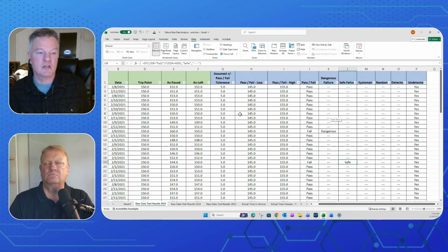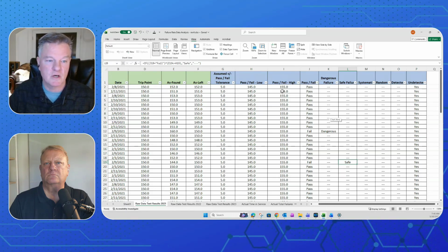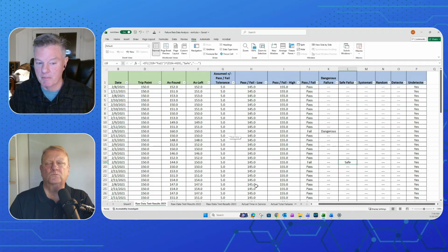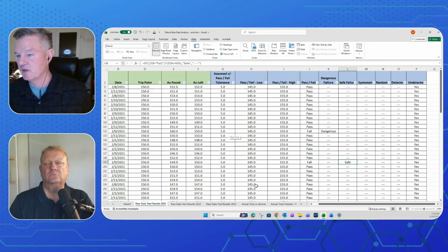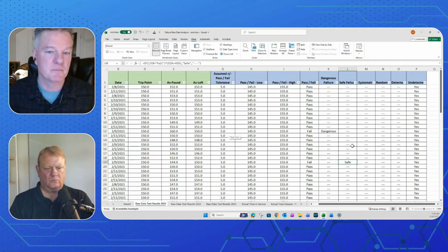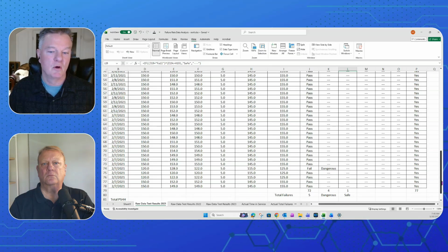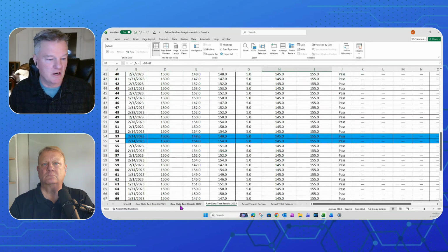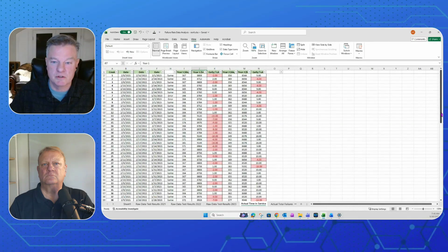Basically, just simply using the pass fail criteria with a tolerance, we classified all the failures. They did not want to keep up with systematic. They didn't want to deal with that. They weren't sophisticated enough. They didn't think they could keep it consistently going forward. So we ran this pilot. They have 274 PD pumps. We only had data on 77 to 79. So I had year one worth of data, year two versus the data, year three. I actually calculated time in service for each one of these widgets.